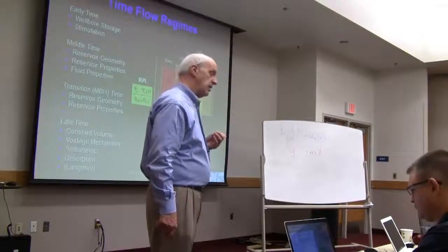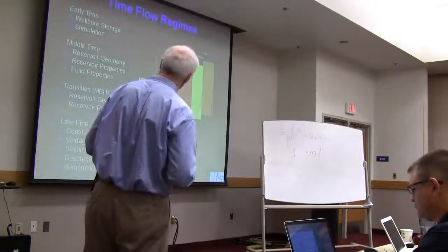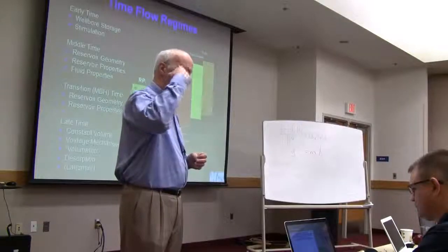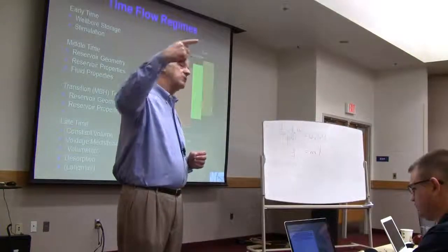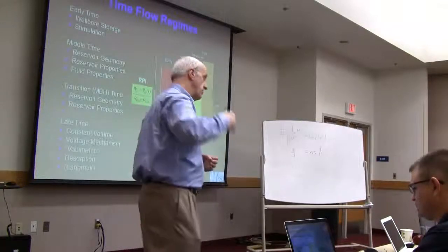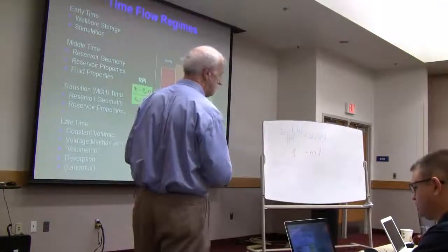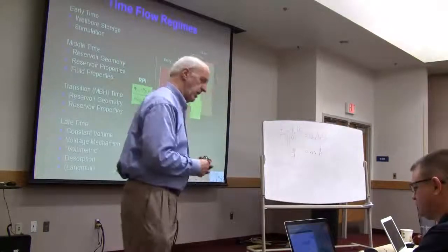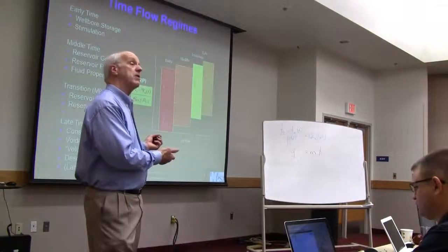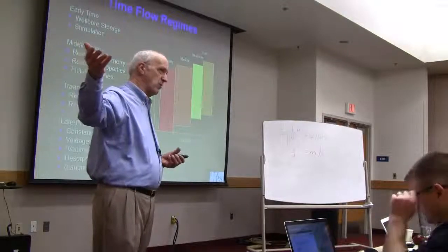That said, I then am confronted by the fact, and this graph, it's a crappy graph, but my intent of it is to try to get you to wrestle with the idea that the way a well ages is strongly a function of its prior history. And so that's really what this picture is trying to engage you in. What I do during the flowback after the frac job will affect the EUR. You say, that's dumb. Of course it would.